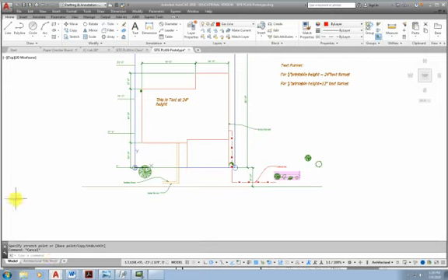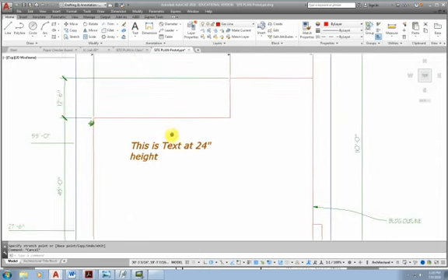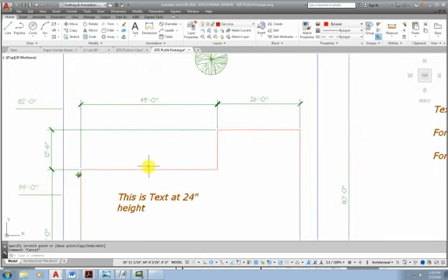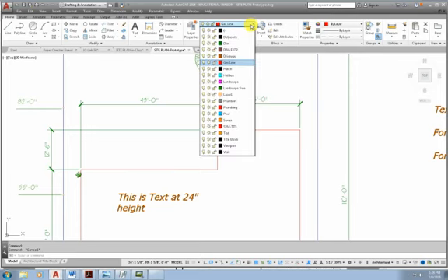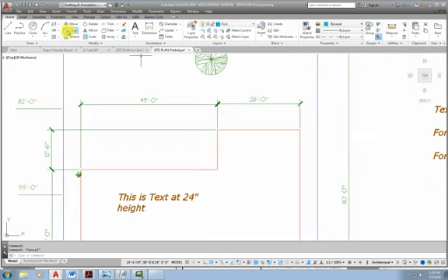It lays out the location for the pool actually from the house as being 9 feet 4 inches from this line and 9 feet 4 inches from this line. And so I'm going to start off by offsetting those two lines. Let's see if I have a pool layer. I do. And I'll offset that with the modify command, offset 9'4".